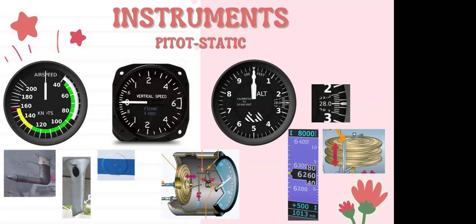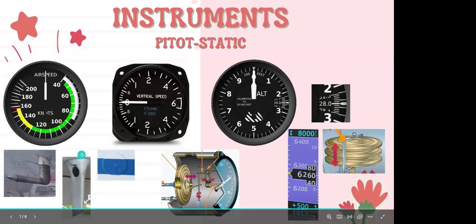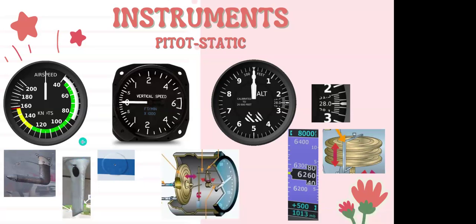But on the Cherokee, we actually have something called a pitot mast, which is this right here. You've probably seen it if you've preflighted the Cherokee. And it serves as both our pitot tube and our static port. So it's one place for all. And that's just an aircraft designer quirk. Most Cessna products are going to have the two separate. Most Piper products are going to have the one, that pitot mast.